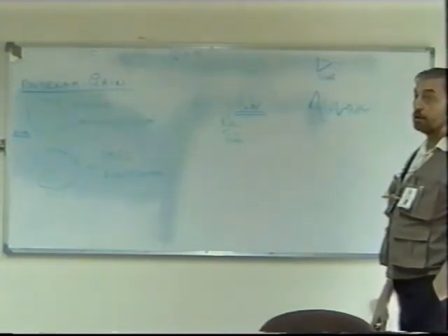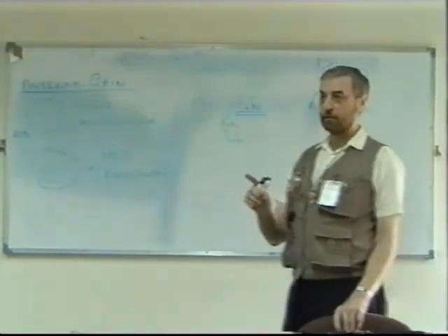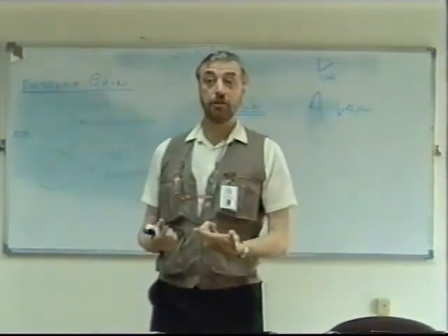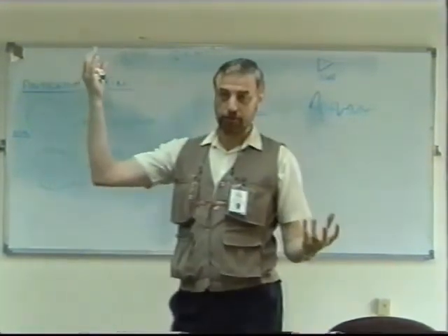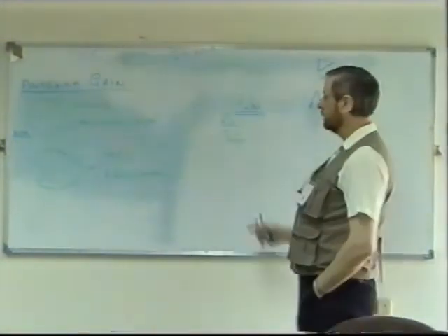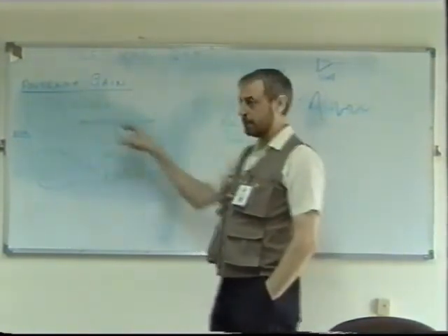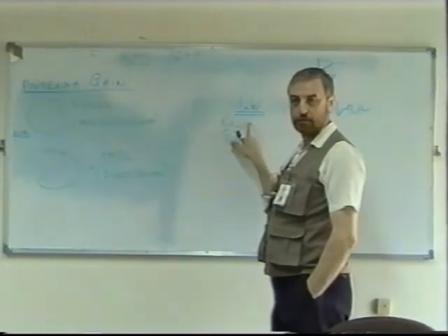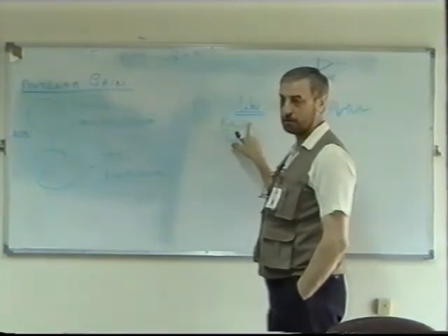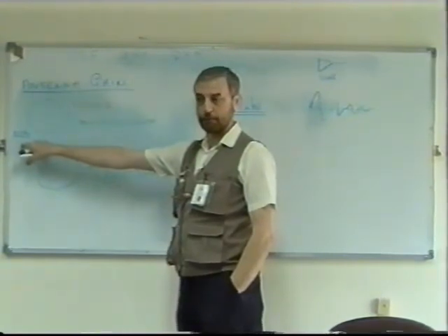So when we want to speak about the range, how far you want to transmit, it's the last distance, the noise. Yes. Now here's where we're bringing into account noise. Before, remember when we spoke about the line of sight, that was just the maximum possible range according to the mechanics of the height of your antenna, curvature of the earth, etc. But now, of course, we see that there's a little bit more to it than that. If I make this signal too weak for this distance, then maybe this power here in the receiver is below the level of the noise that can be generated. And if it is, then it's not going to be sufficient. There is actually a calculation we can use to find out what this power is going to be.